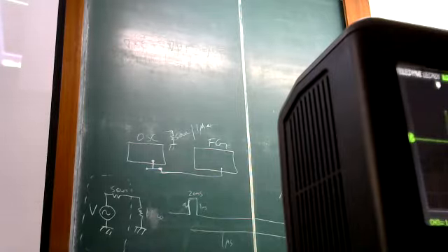Nothing is changing on the back end. The impedance of the source is still always 50 ohms. Whereas when I change the input impedance of the oscilloscope from 50 to 1 mega ohm, it's physically changing. So the signal which comes here will experience a different load across it. Okay, that's important to know because that will determine whether things are matched or not.